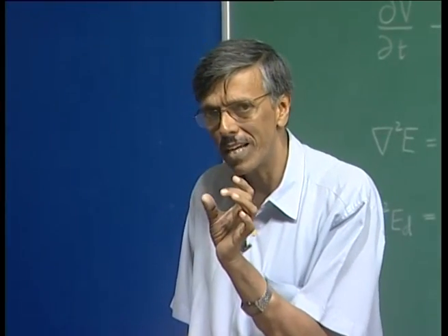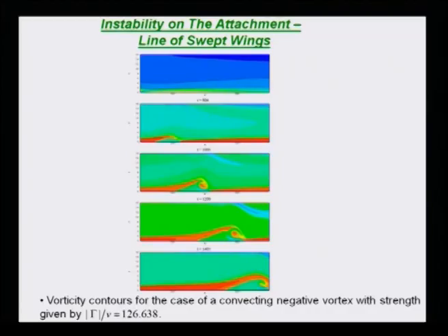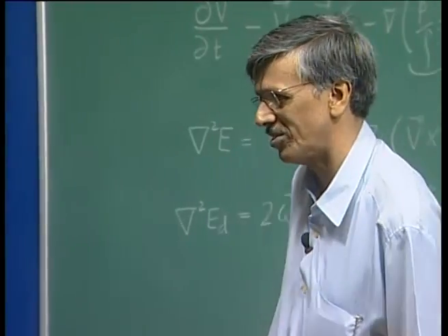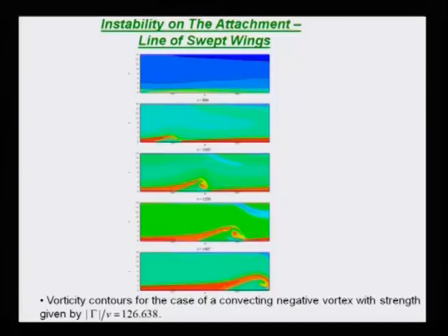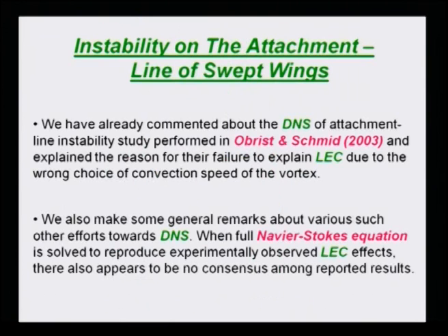So, this adverse pressure gradient is very localized, very localized, and that is what causes a single vortex to be created. You are not going to see a large sequence of vortices. So, that is what you are seeing: with time they just simply pass by and nothing much happens. Flow reverses back to its undisturbed condition, and that is what a good receptivity calculation should reveal. And all these things happen. The top frame is at t equal to 804, the bottom frame is around t equal to 1400. So, in that period of time we see all these things happening.